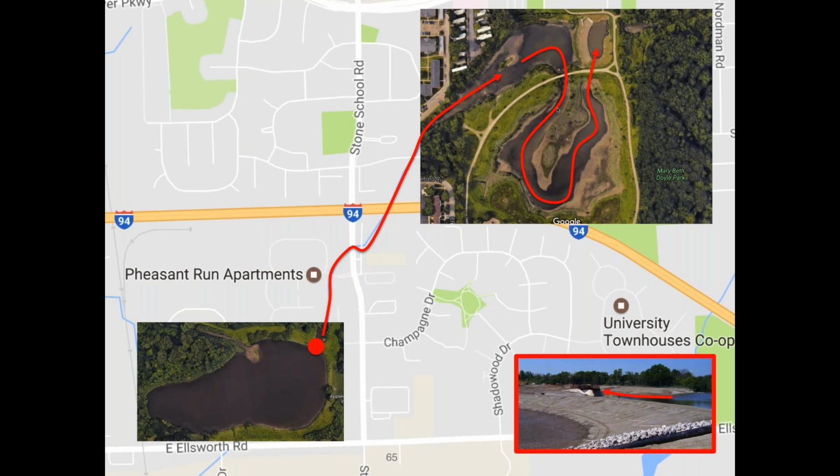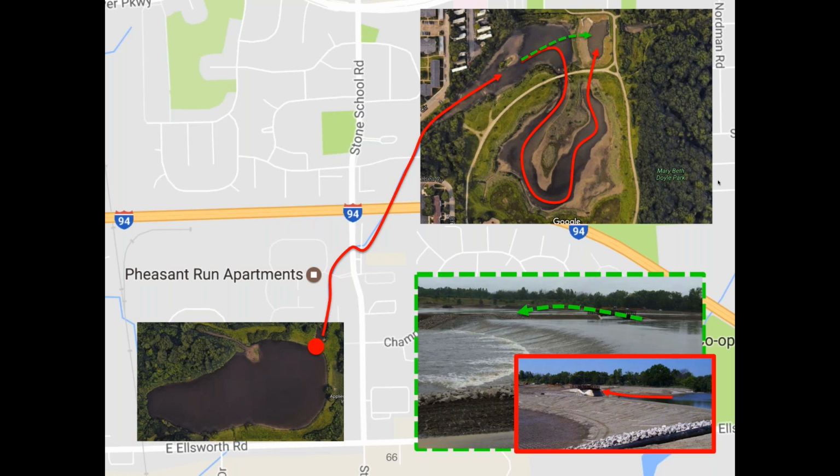So when it rains, you're going to get flows from this site, but also from all the neighboring sites. And what actually happens in a lot of situations, because it has limited capacity, limited volume, you're going to get overflows. So instead of flowing through the wetland and being treated, you have basically water that's overtopping right here, right? That's how the system is designed. So the idea was, could we put a sensor downstream, measure when that wetland has capacity, and actually only then send flows down. So basically saying, let's not control the site upstream just for its own benefits, but let's control it for the benefits of downstream.